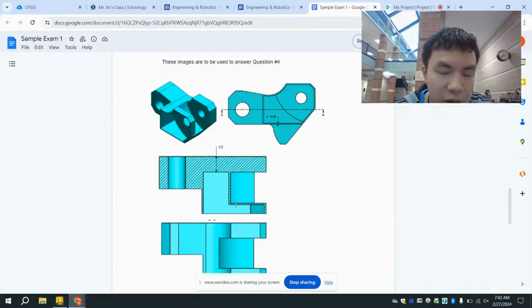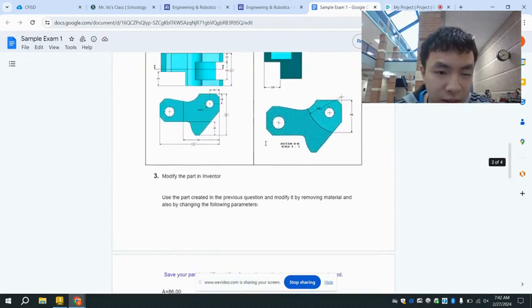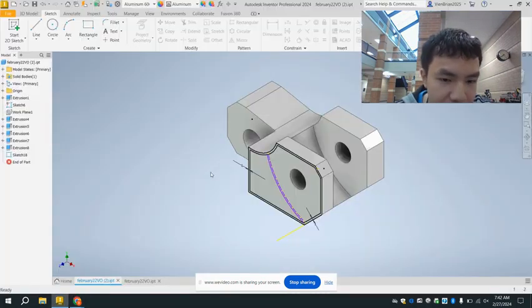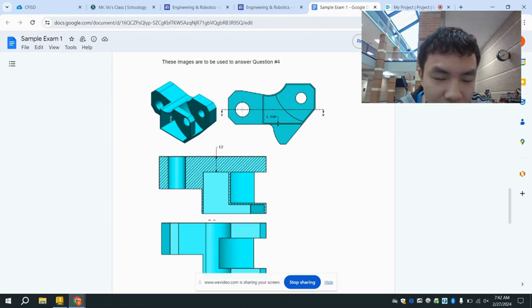So this part 4 uses the same dimension as part 3. So as soon as you get the dimension, you refer back to part 3. Now this extrusion right here that goes all the way in, it reaches only that part you see right here. It only reaches the back of this back hole right here. This should extrude back here to this arc right here. This should not be extruded. So don't do that.